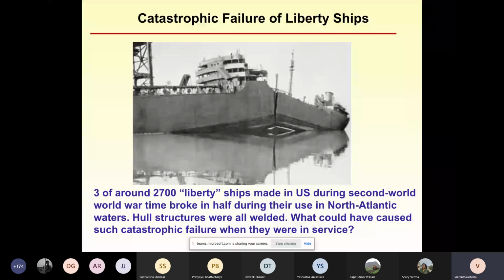Riveting was very popular up until some 50-60 years back. But then riveting was taking a lot of time. Have you ever seen thick steel plates being riveted? Some olden time videos. Basically, you would have two plates with matching holes made, and then you take these iron rods. You would heat them until they are red hot, and then throw them from the point where you are heating it to the point where it has to be riveted.